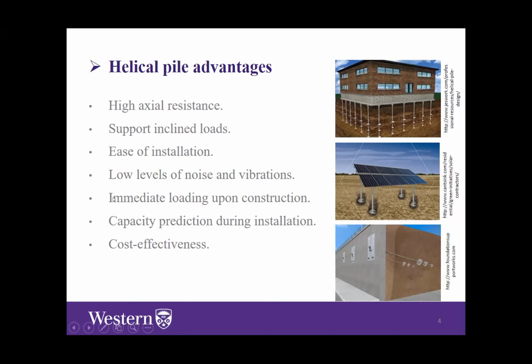One of the very big advantages also is that it allows immediate loading upon construction. So in contrast with concrete piles, where we have to wait for 28 days until we can load them so that the concrete can be cured, for the helical piles, once we install, we can apply the load directly to the pile, which makes it very useful if we are going to deal with some existing foundation problems.